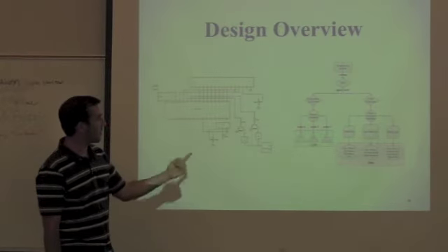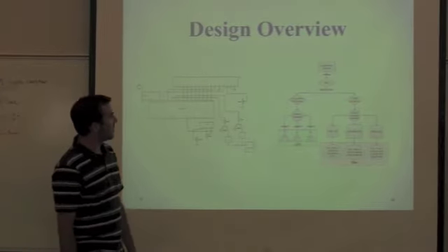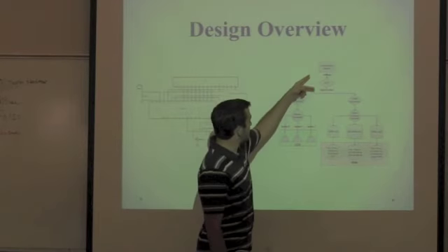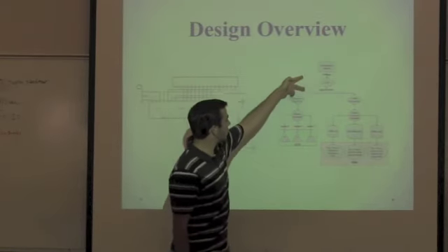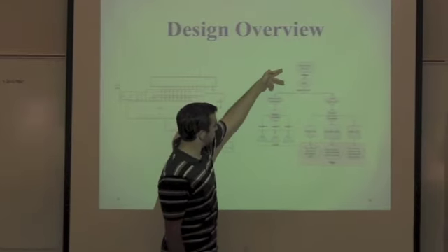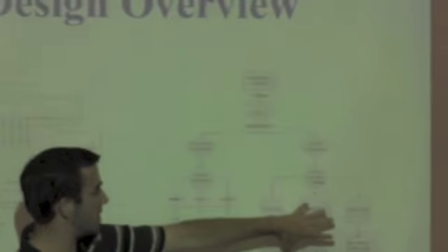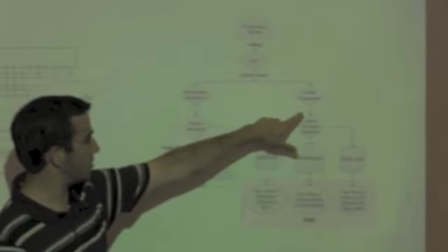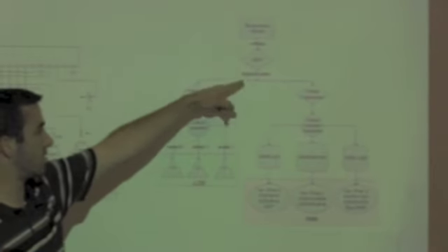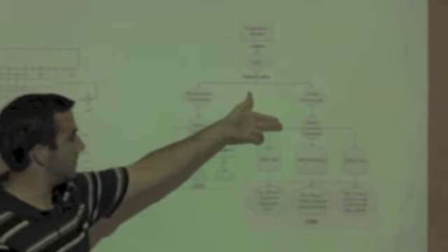And the software flow originally was just this left half, but we included this, which has the pulse width modulation conversion from the digital value of the ADC, and then that went into an output compare controller.